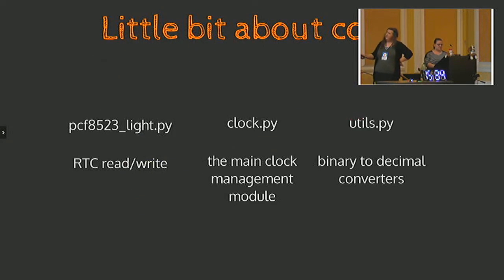The first file here is called PCF8523 Lite. PCF8523 is the part number of the RTC, and Lite because we had to write a lighter version of the existing driver. The problem of the provided driver is that it treats the date time as a single time struct at once, and that takes a lot of memory for a little device like that.